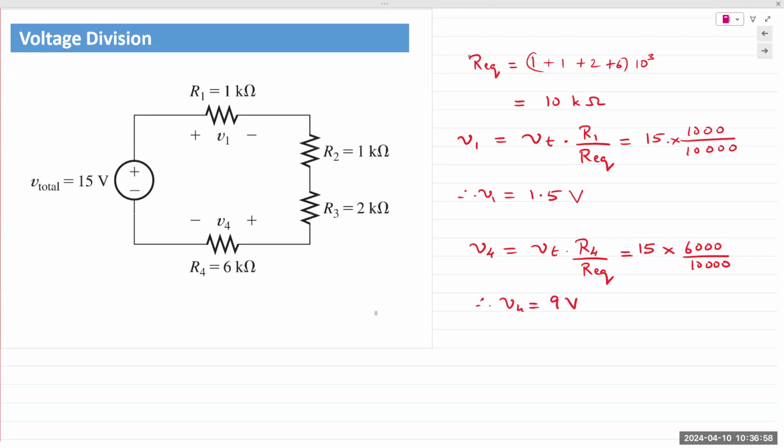Take 10 seconds, think over it. Let me know if anything doesn't make sense. Okay. Voltage division and current division are shortcuts. The shortcuts are derived from Ohm's law. It allows you to skip over a step in your analysis. We do not have to find the current in order to find the voltage. So it allows us to skip at least one step.